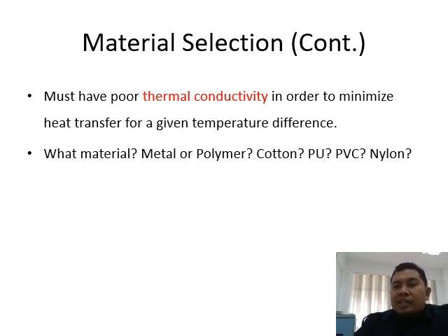For the oil and gas piping, you have hydrocarbon flow in the pipe. Usually, the temperature for the hydrocarbon moving in the pipe will be like 200 degrees and above. So to prevent this hydrocarbon from solidifying in the pipes, you need to have a thermal blanket, which they call insulator or insulation lah.